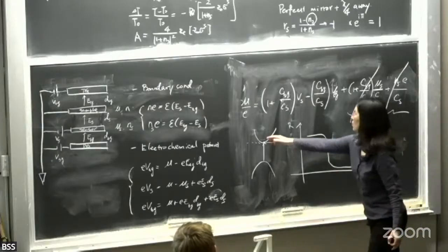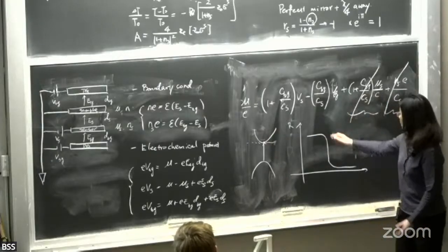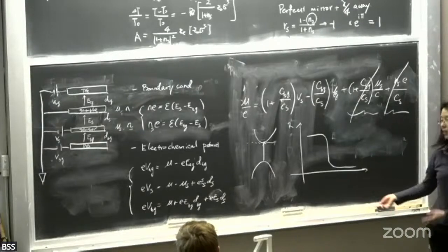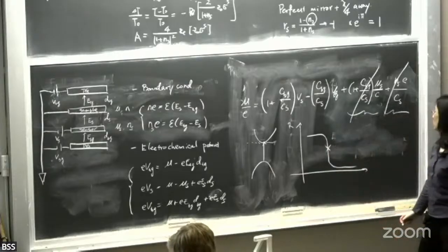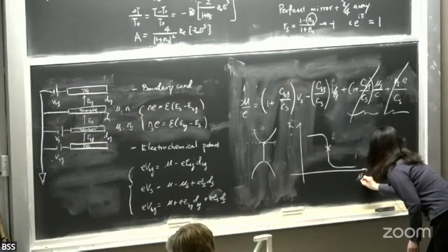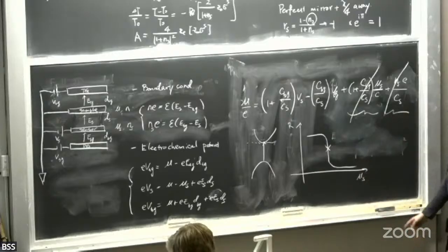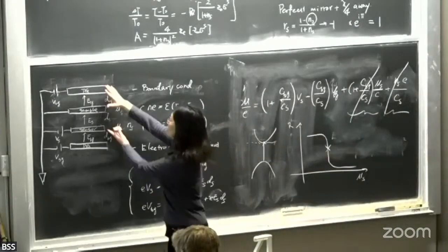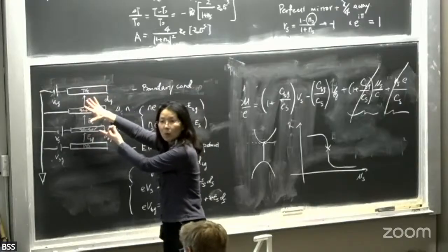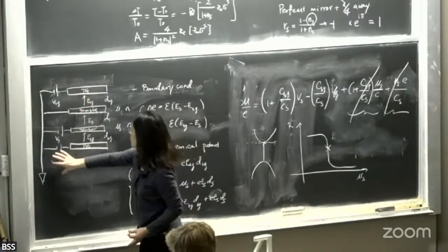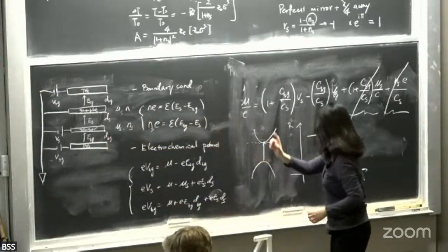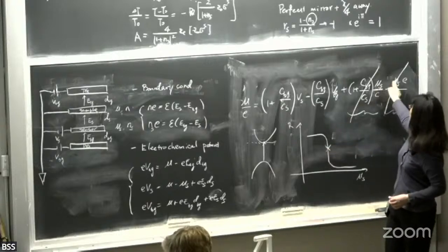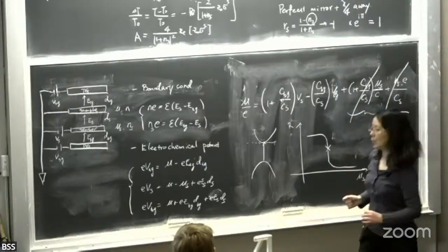And this is the point when you block the transition, right? So this is a very sharp edge, and you consider this like an edge detector. So this is mu s, right? Set your reference point right here. And then every time you do something to change the sample property, you use this backgate to bring the chemical potential of your sensor back to this point to make this constant. So this is the measurement scheme.